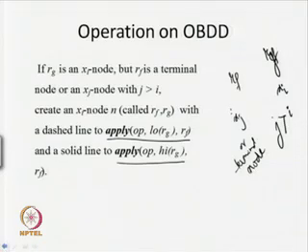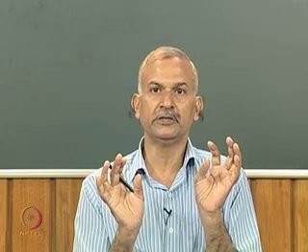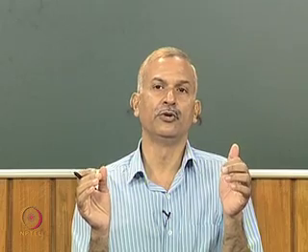So, these are the rules that we have here. Now, just see that we are going to take two ROBDDs, and traverse them from the top, in a top-down approach. If both are terminal nodes, then we are going to apply the operation there, because we know the values: 1 op 1, 0 op 0, 1 op 0, or 0 op 1. We may have 4 conditions.